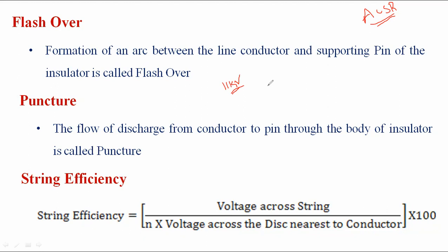And another one, the strain type insulator. It is similar to the disc type insulator, and is used wherever the tension is more, such as dead ends, cross sections, and curved positions. It is used for the transmission line, and the individual disc capacity is 11 kV. Beyond 11 kV it is not economical. Similarly, based upon the operating voltage, we can connect n number of discs in series.